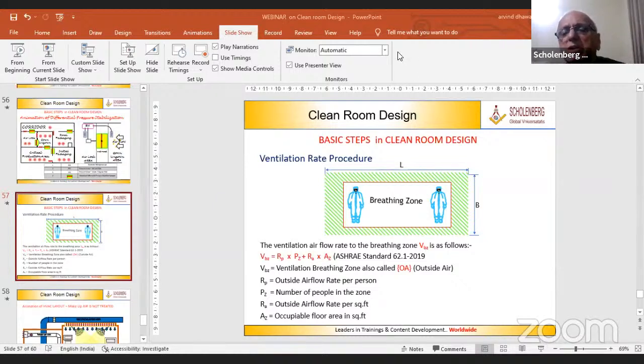Some more questions out here also. What should they have for an operation theater? And how do we calculate filtration air quantity for a clean room? That filtration rate chapter is there in this course material. So may I know what are the common face velocity baselines? This is standard for all AHUs: 500 FPM suction and 1500 FPM discharge.